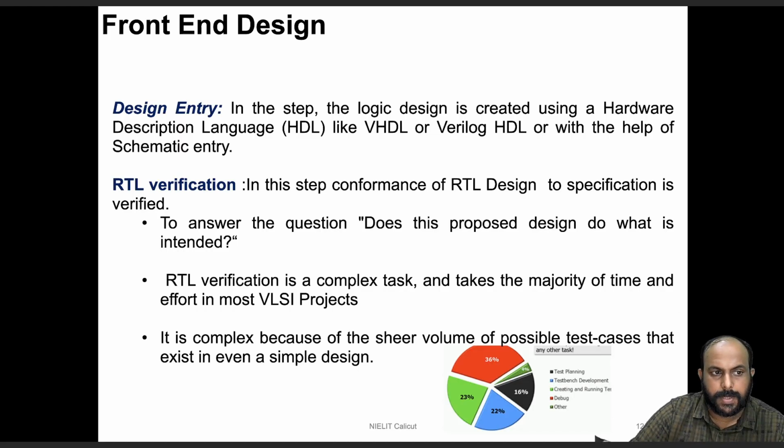Design entry is, as I told, representing the design with the help of hardware description languages, and RTL verification is all about finding the answer to the question of whether the proposed design will do what is intended by the customer or not. RTL verification becomes a complex task out of the sheer volume of test vectors or test cases that the verification engineer has to apply on the design so as to verify it as exhaustively as possible.